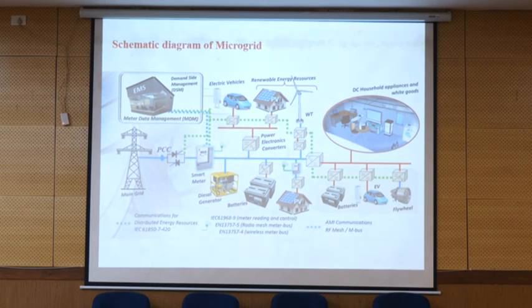So, but assuming that you are going to, for example, supply by these storage devices, you have a DC AC converter. This converter should work as a grid supporting, okay? Because it should be able to create the voltage and frequency we need.